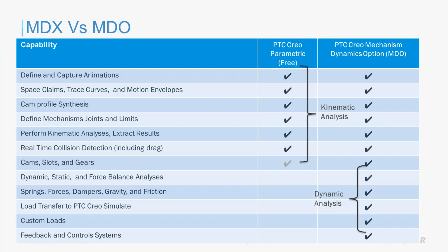It's pretty straightforward. You would add your constraints as connections, which is essentially a joint between two parts, right? And once you create the joint, you would just run a kinematic analysis for a certain amount of time. And you even have the capability of exporting a movie file out of that, right?